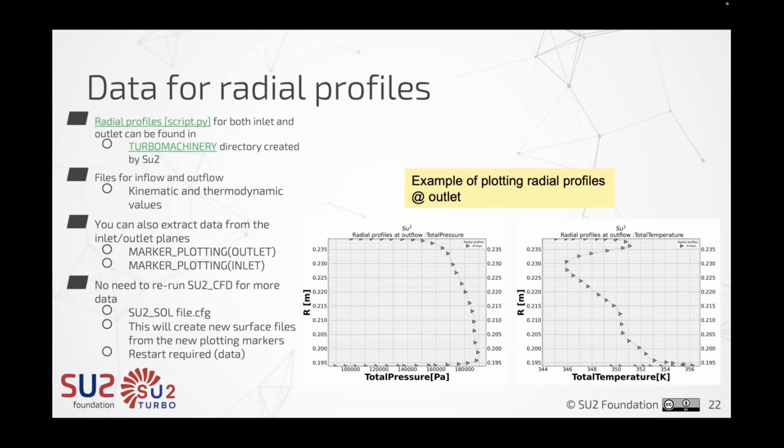Structured multi-blocking is, for example, like when Alessandro showed the radial cuts, it's a no brainer because your radial cuts are based on your IJK coordinates. If your radial distance is in the J coordinate, then you just select the J coordinate and it'll do the cut, and then you have your blade to blade. Whereas now in unstructured meshes, you have to go into the math and script that whole thing. So I have to build this whole thing, and I think it's just a question of experience.